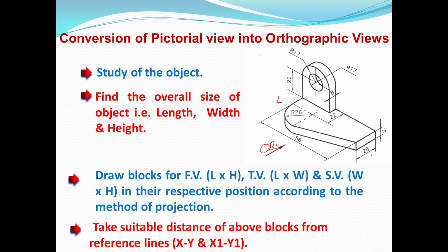This is the left side and this one is the right side. If this is the semicircle arc, this one is the diameter part passing through the center. So the center point is 17 mm from the left side, and 17 mm from the right side. If this is the rectangular block, length by height for the front view, we can draw a line, or locus of a line, at 17 mm from the left side. On this locus there is the center line.